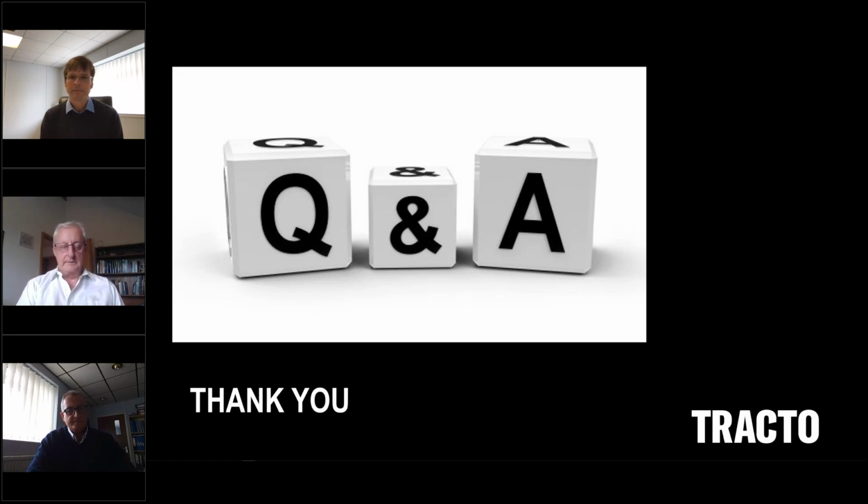I have just one last question, and Roger, again, in the presentation, you touched on cover and relatively shallow depth installations. Is there a rule of thumb for a minimum cover depending on different soils or so many diameters? Not really. It is not like it is with the soil displacement hammers, where we need a minimum of 10 times the diameter of the machine as cover. We haven't got a rule of thumb as such.